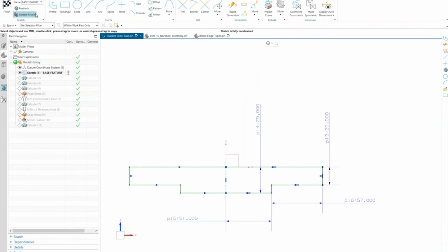In the environment, you get this dynamic Home tab, and you have curve creation, curve editing, and different operations. Here, one of the things I've utilized is the symmetry that I have in this bracket. I've created my initial sketch around the origin point so that I can then use this Z-axis and the make symmetric constraint to essentially mirror over those curves.